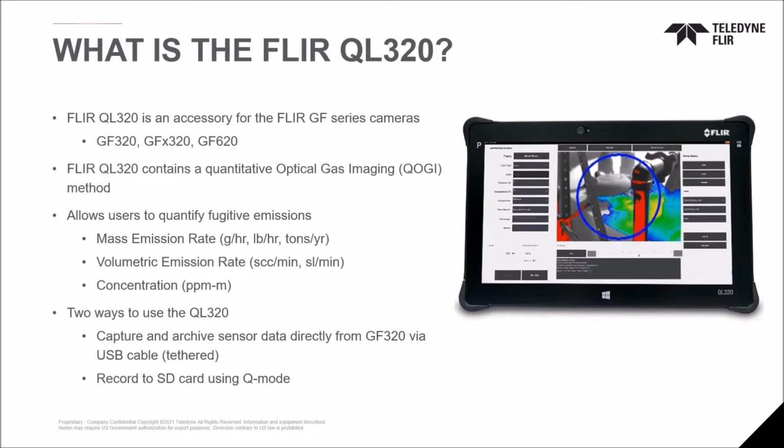The world has always accepted a concentration, which a challenge of a concentration is it is a measurement at an individual location, not as something changes from one location to the next. When you use a sniffer, you are measuring exactly where the input of that sniffer is only. And that doesn't truly tell you what's happening as a leak is moving.